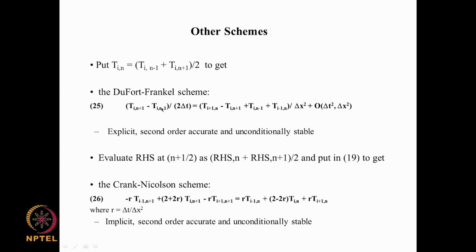Okay. So, and we are looking at Ti^(n+1) here, and this is given in terms of Ti^(n−1). So, this is an old value. So, this is, we can say, is known. Ti+1^n, this is the previous time step value, so known. Ti^(n+1), so this is what we are actually trying to evaluate. So, we can bring this here. So, this is not a new term. Ti^(n−1), this is old value.